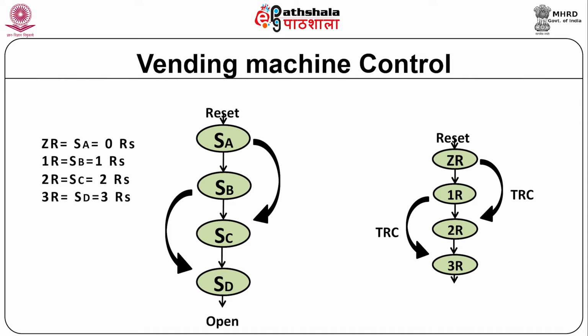that is 3 rupees are inserted. Now let us find out the possible ways or paths that the vending machine can take to get into these states. Considering all possibilities, the vending machine starts in the initial state. ORC, that is 1 rupee coin is inserted, TRC, 2 rupees coin is inserted, default, nothing is inserted. From this list, it is clear that there are 4 states and 3 possible paths from each state. It is now needed to depict which states are connected by which paths.